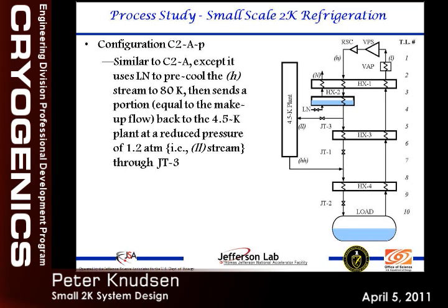Other than that, it's very similar to the one we looked at before. I will mention too, there is a loss mechanism right here because this is high pressure, and we're having to inject this into the low pressure stream of the liquefier. Otherwise, it's possible you could match it to the high, but it's difficult, except in a specific instance, to do that. So we just assumed that the high pressure was dropped to low pressure.